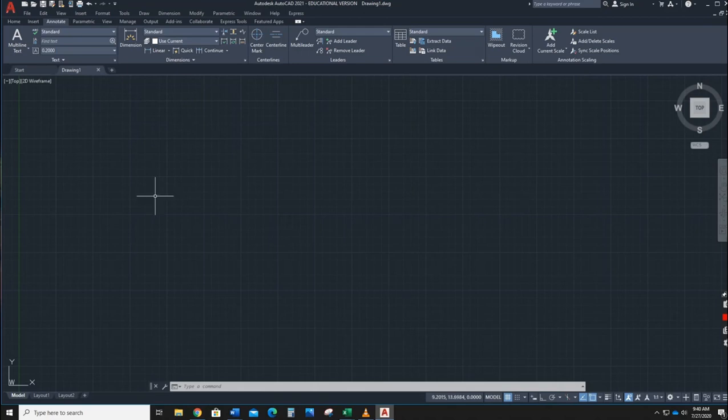When we create drawings, there are two places that we're going to draw. One's called model space. That is where we're at here. It's the black background and it may or may not have the grid depending on what we want it to do. Down on the bottom left hand corner you'll see three tabs.